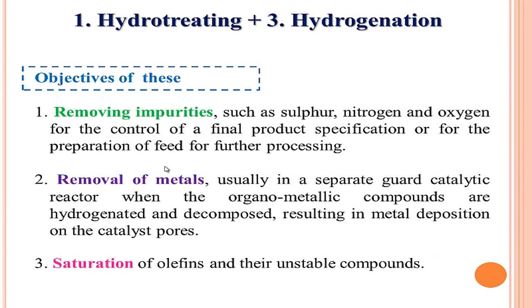Let's focus on hydroconversion in terms of hydrotreating and hydrogenation first. The goals are to remove impurities, sulphur, nitrogen, oxygen, and metal trace to obtain good products that meet the standard. By the way, some unsaturated hydrocarbon can be adjusted for the saturated hydrocarbon products.